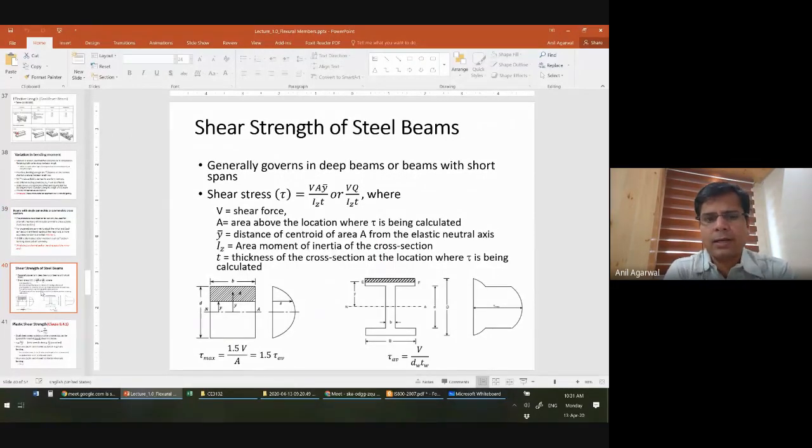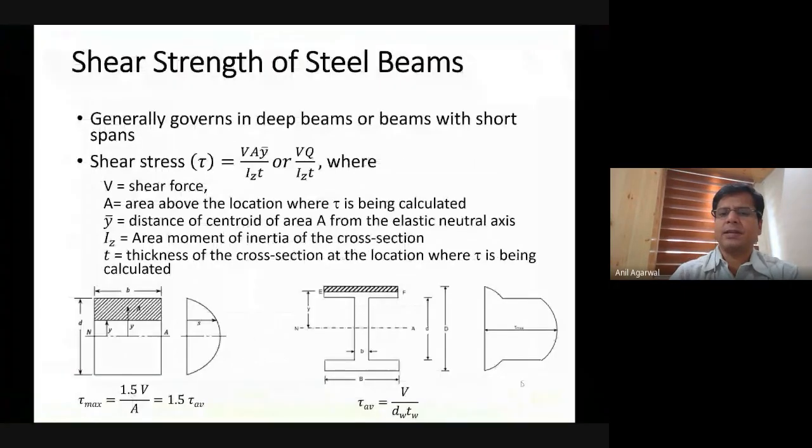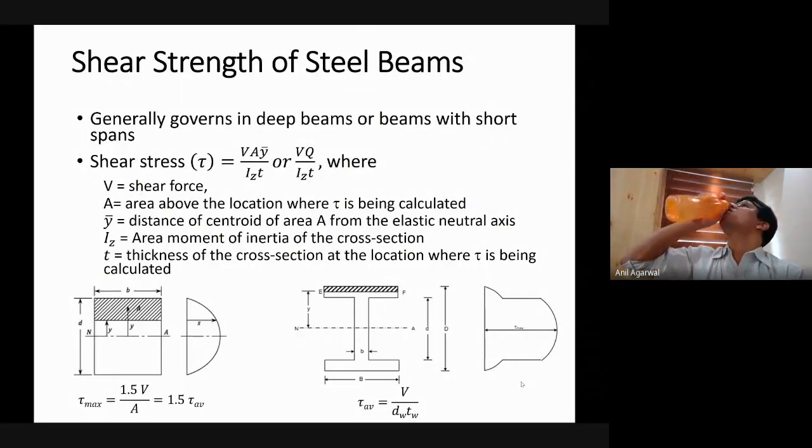One thing that I had discussed very briefly in the beginning was the shear capacity of a beam, and we had said that you calculate the shear capacity by assuming that only the web carries most of the shear force, and you know at what stress the web would yield in shear. It was also required for us to calculate the interaction between the shear force and the bending moment capacity.